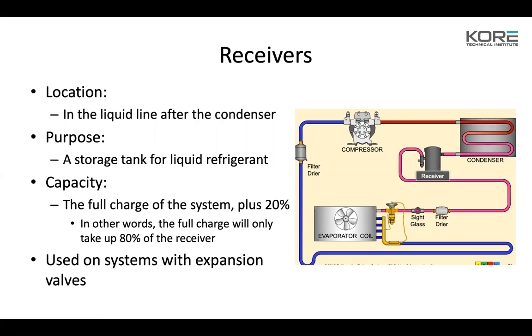As you guys go out today and get called out for your refrigeration calls, there's going to be a lot of gas out of the systems in the next few days with these really cold temperatures. The reason is that any repairs we made during the summer, we put in enough charge that we thought was adequate for the time of year. Now that refrigerant is starting to stack because of the head pressure control valves. It's stacking in those condensers, whether it's a headmaster on a smaller system or a holdback valve on a larger system. Those regulating valves are actually stacking the condensers to eliminate condensing capacity.